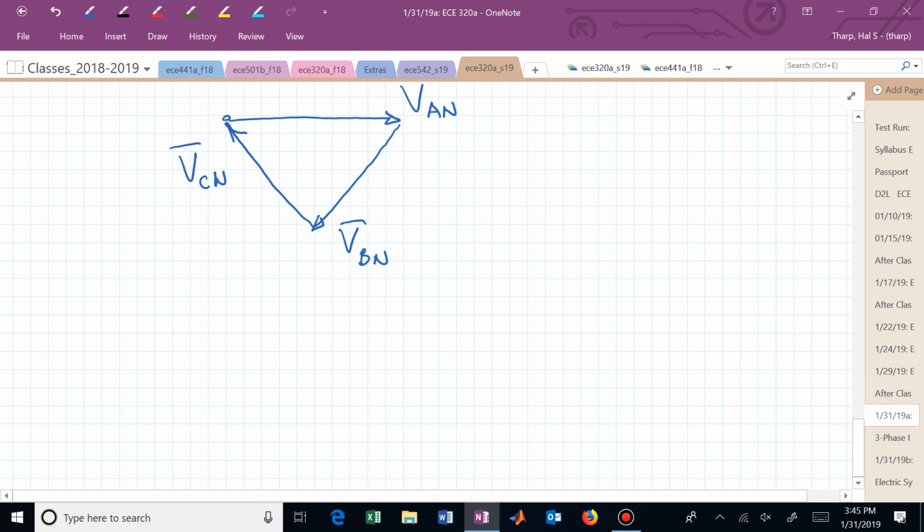If you put it across a resistor, it would look like 120 volt DC is the power that resistor would sort of feel. It would get hot at the same rate or in the same way that a sinusoid of 170, 0 to max, does. That's what the RMS is telling us, that on average this looks like 120.